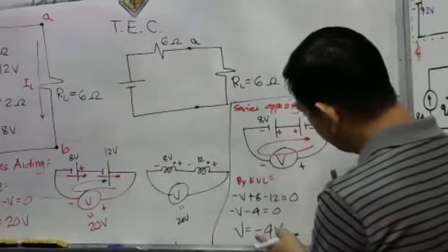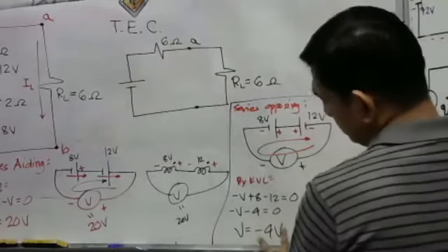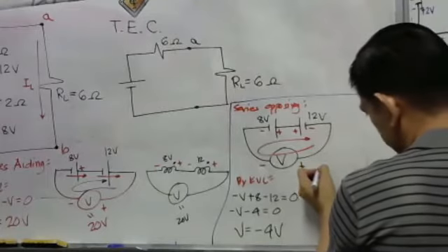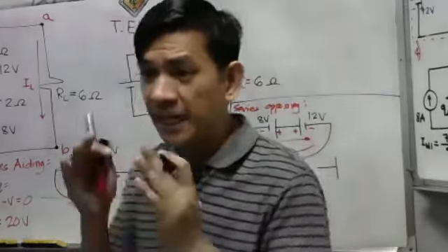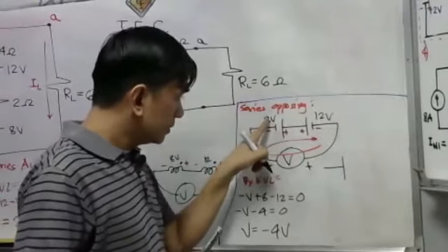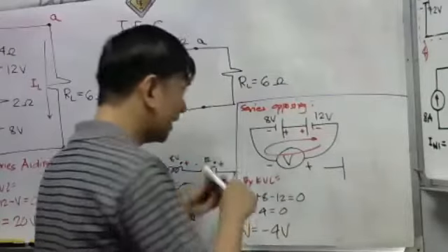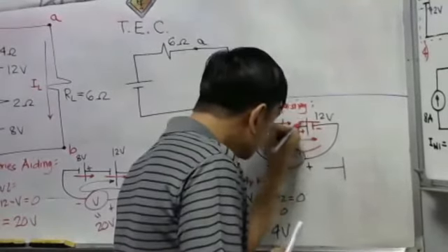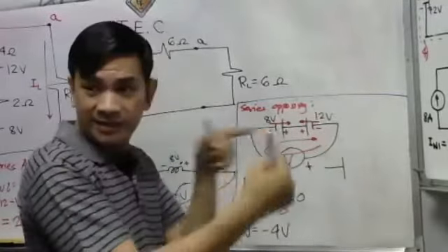So that will become a negative. Meaning, this will just have an equivalent circuit. This is negative 4. So this will give this circuit, following which voltage has the higher value. 12 volts compared with 8. So this will follow this connection. Why is it called they are opposing? Because the current for 8 volts must leave on the positive terminal. And also this, the 12 volts, it leaves on the positive terminal. They oppose each other. Okay?